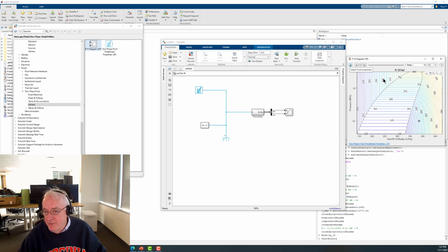And with that, you'll see that measurement superimposed on the thermodynamics for R1234YF. What we see now, where if this was water we'd be, I'd say, subcooled, here we're superheated. That's on the right side of the dome of this thermodynamic chart.